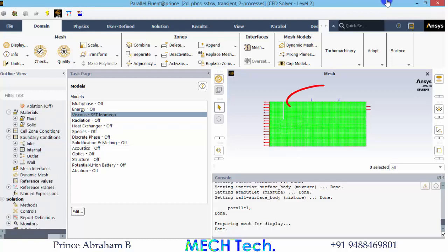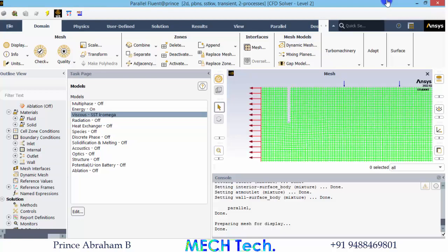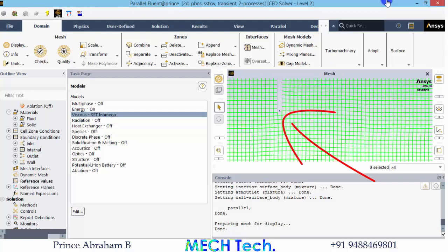So we have inlets, these two are inlets and this is an outlet, but however these are not simply inlets, because these are recirculation zones. An air conditioning system receives the air from the room and then cools it, and again sends it to the room. So that is actually a recirculation boundary. Similarly here we have a boundary, that is the air curtain inlet, that is also a recirculation boundary, because the air is not coming out from the system entirely. The air is drawn from this room, then compressed and blown inside the room. So we need to have a recirculation boundary.